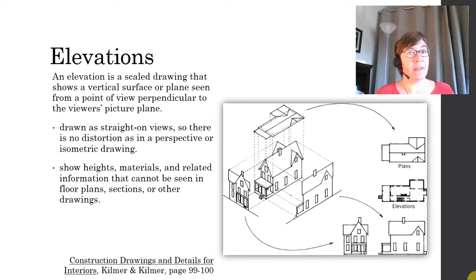And why should we draw such a thing? The reason for drawing elevations is to show any heights, to show any materials, and just any other information that can't be seen in other drawings in your construction set, such as floor plans and sections. So let's take a look at this illustration here.